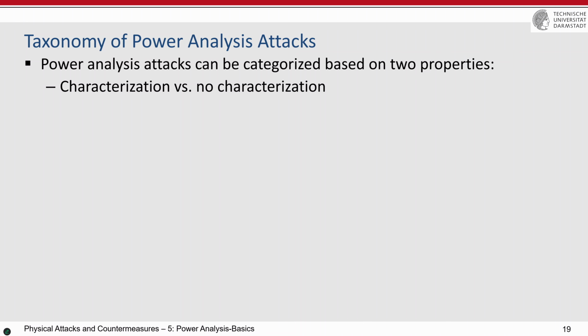And then I try to understand and learn what is the relation between the power consumption or such information of the device when I can control everything, when I can control the key, when I know the plaintext, when I know the intermediate values, and so on. Once I learn this, which is also called profiling attacks, or attacks with characterization, then with this knowledge, I come to the target device and try to perform the attack on the target device, with all the knowledge that I got from another device which is similar to the target device, while I could control all its intermediate values.